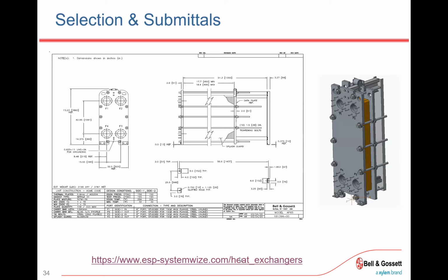The other thing is they categorize the toxicity of different fluids, and surprisingly, propylene glycol is in a very low category. I'd be more concerned about everything else in the system, all the magnetite and iron oxide and debris, and sometimes you even have bacteria growing inside of the pipe. But yeah, when you select the NSF, it just makes sure that your nozzles, or your connections to the unit, are also stainless steel versus the standard.